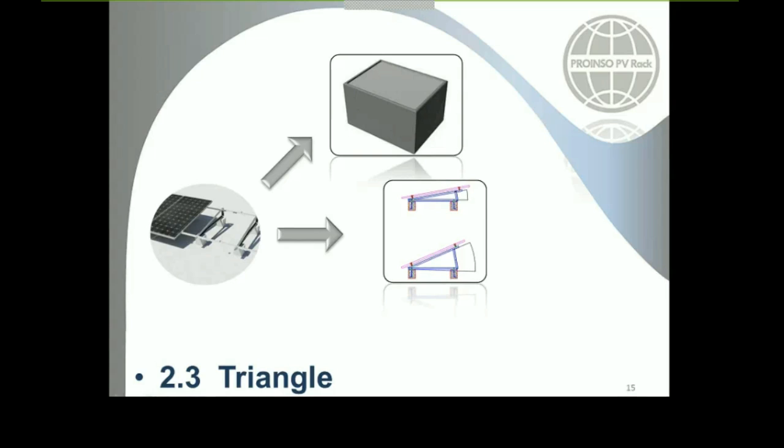If you put, for example, some additional rails here on the surface, connecting one portal frame to the other, you have a surface where you could put all the weight necessary for the specific location, considering the wind loads, and that's all. It's so easy to fix this kind of thing. We were thinking of doing it with concrete slabs because it's the worst case.